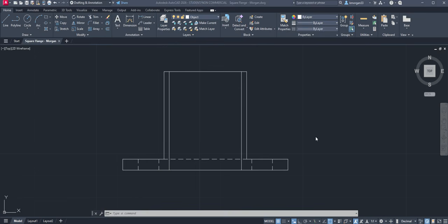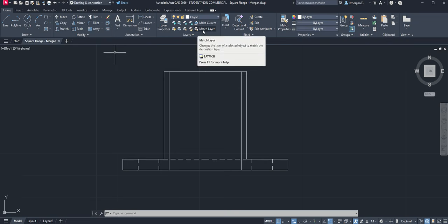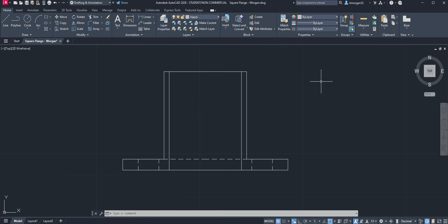All right, now we will get into the hatch command. Let's go ahead and erase all of your previous commands. Make sure no objects are selected, and we're on the object layer for now. Then on the ribbon, choose your Home tab, and go all the way to the layers again. This time we're going to change our layer to Hatched. You're going to get this little gray hatch layer right up there, so we're now on this layer instead of the other one.